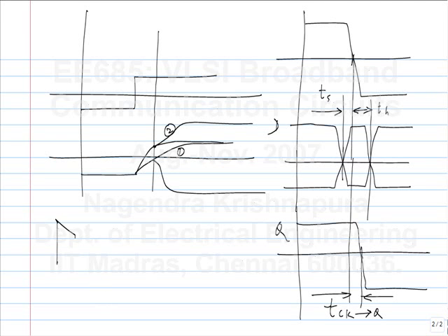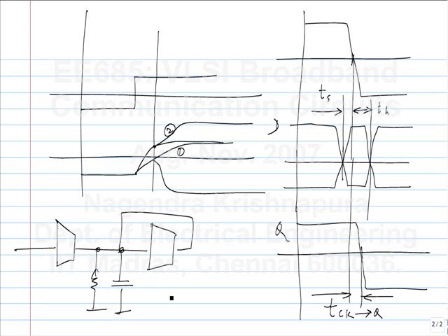So if you look at the system, previously I drew it as though only one of these transconductors is active in the whole sample phase and another one in the hold phase, but that's not true. For a period both of these will be active, and essentially the GM of this goes from the maximum value to 0 and the GM of this goes from 0 to maximum as you switch the clock from sample to hold phase, right?